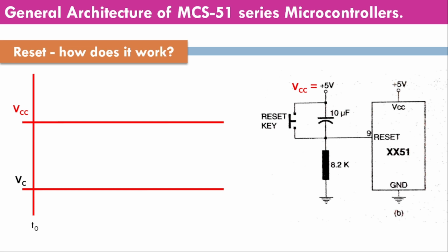Upon supply voltage activation, it swiftly reaches the positive 5-volt level, resulting in a rapid increase with a high-frequency response. Consequently, the capacitor's reactance is minimal due to the high frequency. As the voltage stabilizes, it transforms into pure direct current, DC, and the capacitor gradually charges in line with the time constant illustrated in the figure.